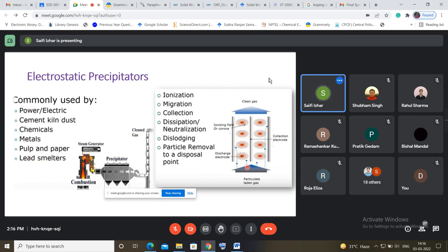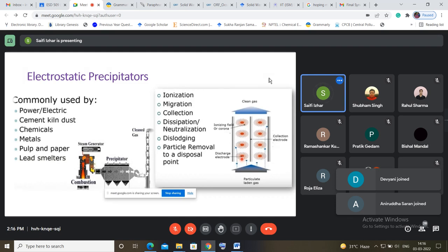electrostatic precipitator, because of the difference between plus and minus, that is set up. So the particles enter this inlet in the gaseous stream. Consider this red as a solid particle. The discharge electrode creates a charge on that particle.